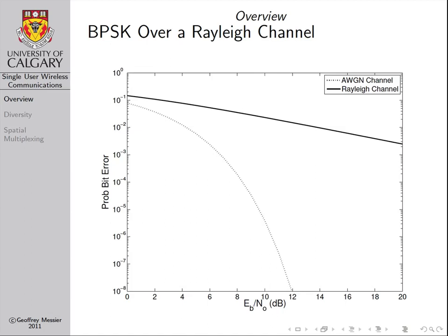Basically, when somebody is trying to use this type of bit error rate versus signal to noise ratio plot, you would essentially do a link budget calculation that uses channel attenuation to figure out what your received average Eb over N naught would be.